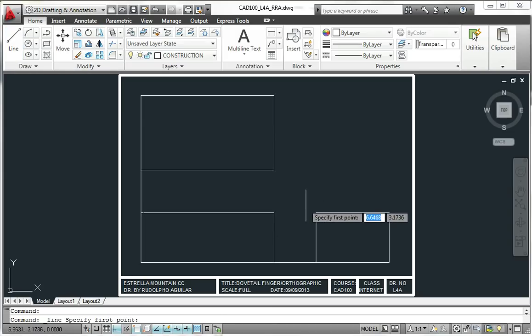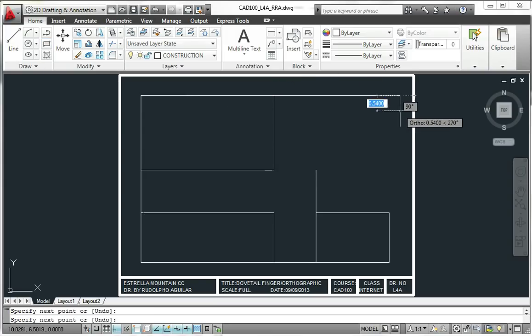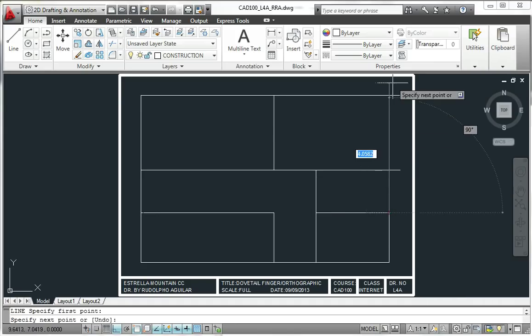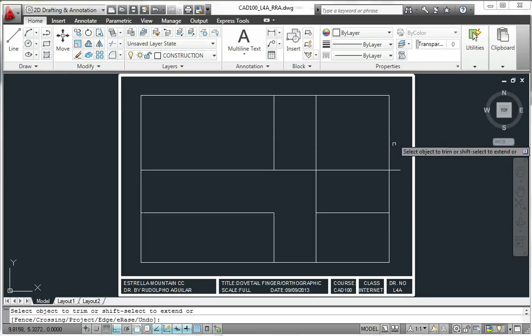You'll be learning what's called a projection box. Let's draw that as well. The height of part is, of course, 1.5. The projection box, I'll demonstrate with lines first. Transfers information from the top view to the right side view, as you would expect. Notice how it's snapping to intersections and perpendiculars. I could have also drawn this with the rectangle command, but for now I'll just trim off the parts.